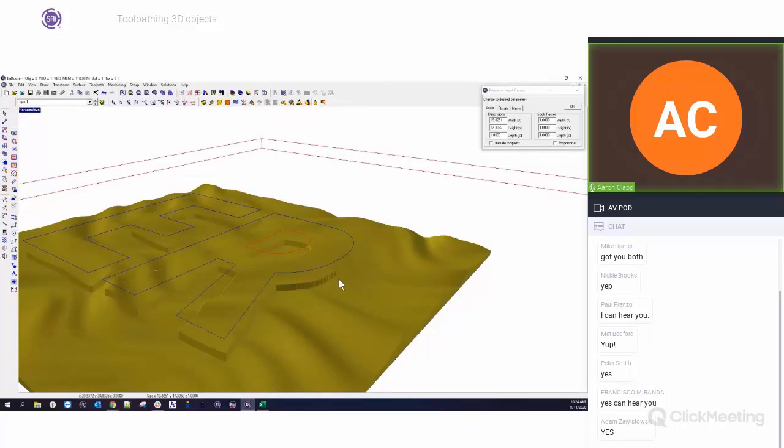This is just the nature of a large machine getting a bit and going as fast as it can, or whatever speed that you're setting it to, and then having to lift all of a sudden very quickly. You're going to end up with a little bit of a ramp up right here. So you're not going to get that nice clean, crisp edge.